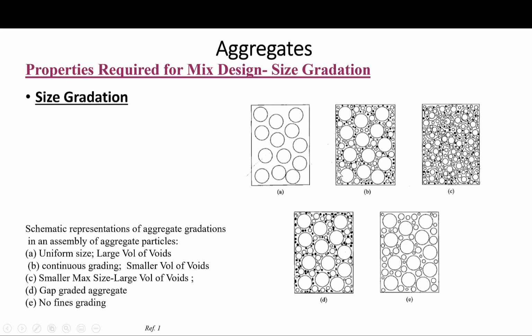Okay. So when we use a range of sizes, the smaller particles, as you can see here, can pack between the larger particles, as shown here. And basically, by doing this, we decreased the void space between the particles, and we lowered the paste requirement.